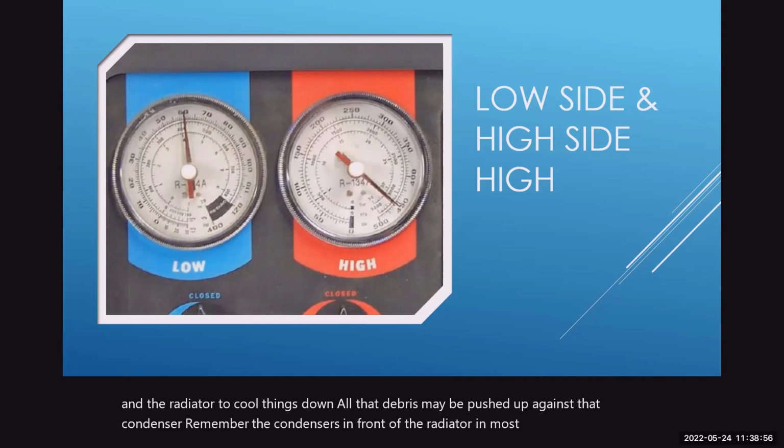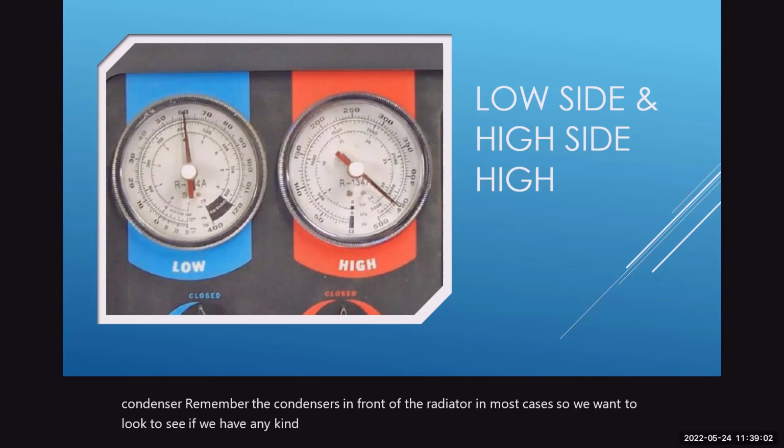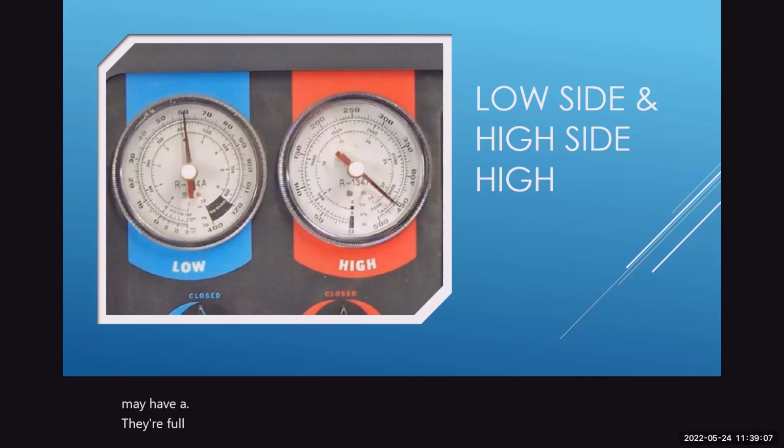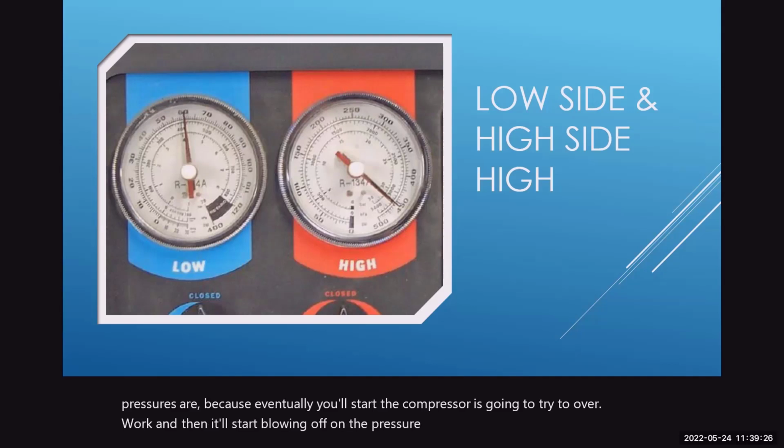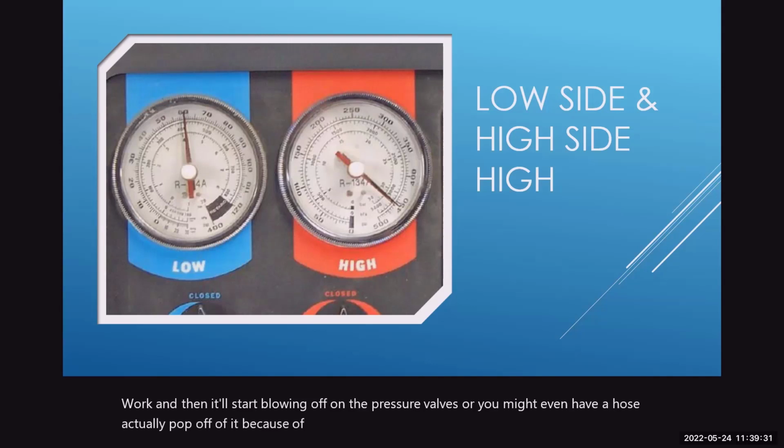So we want to look to see if we have any kind of airflow problems, is what I'm trying to get into. So we may have an airflow problem against the condenser. Now, I'm really concerned about how high these pressures are, because eventually the compressor is going to try to overwork, and then it'll start blowing off on the pressure valves, or you might even have a hose actually pop off because of this high pressure. If it has any weak spots, it'll find a way.